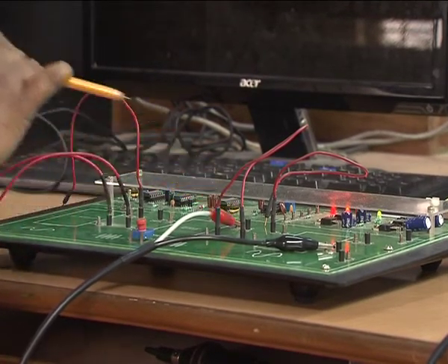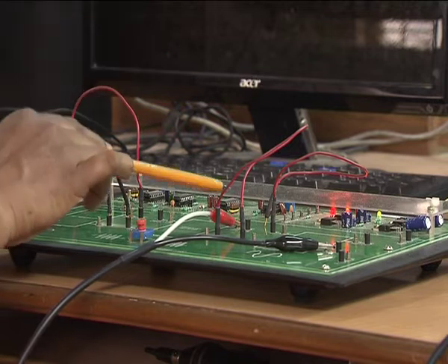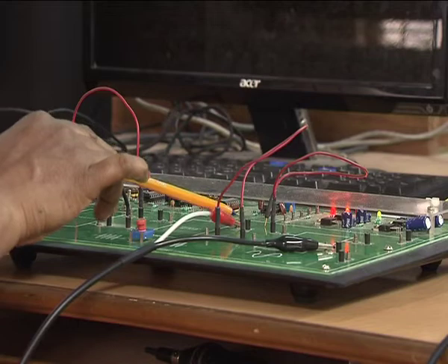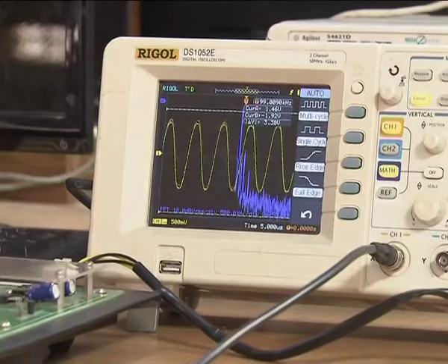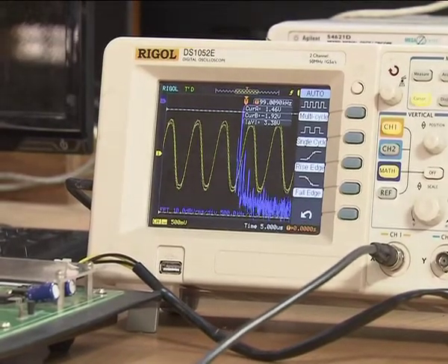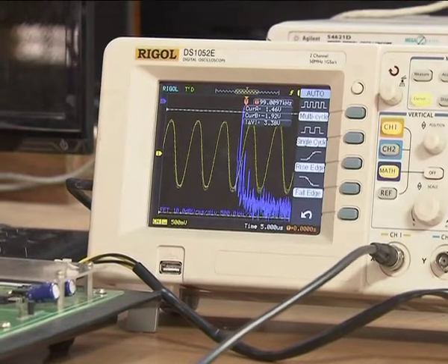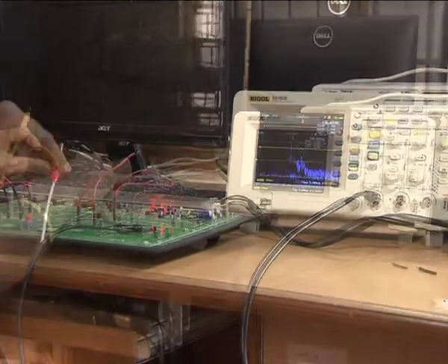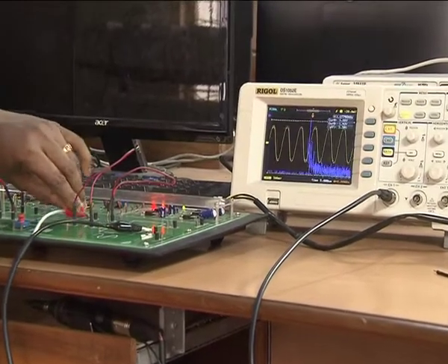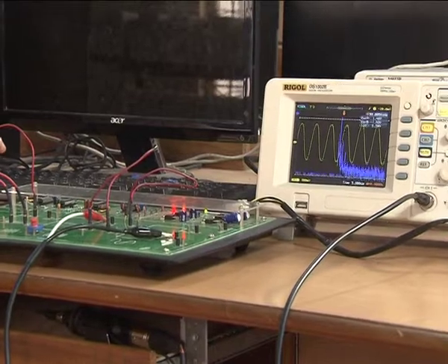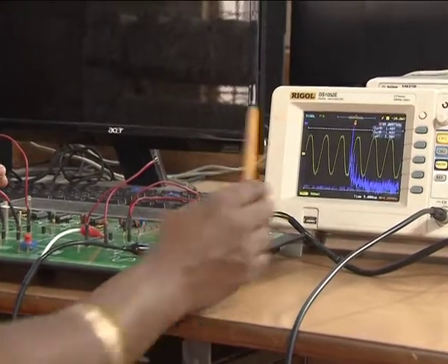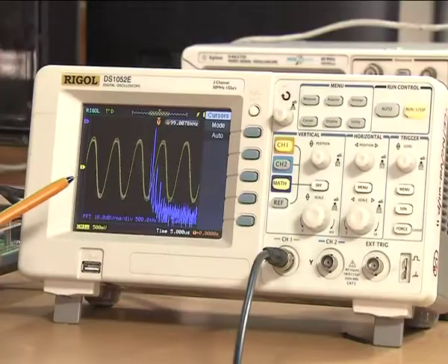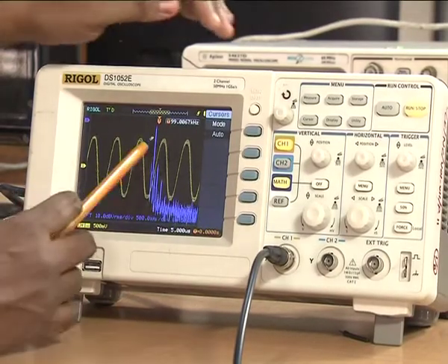So, at this place, without giving any input, I am just seeing what output is produced at the output of the frequency deviator, or the voltage controlled oscillator. The output can be seen using the CRO or a digital storage oscilloscope. Now the probe is connected to the modulated signal output. After connecting the probe, you can see the free running frequency of the VCO in the DSO. This is the sine wave generated by the VCO. The free running frequency of the VCO is about 99 kilohertz.